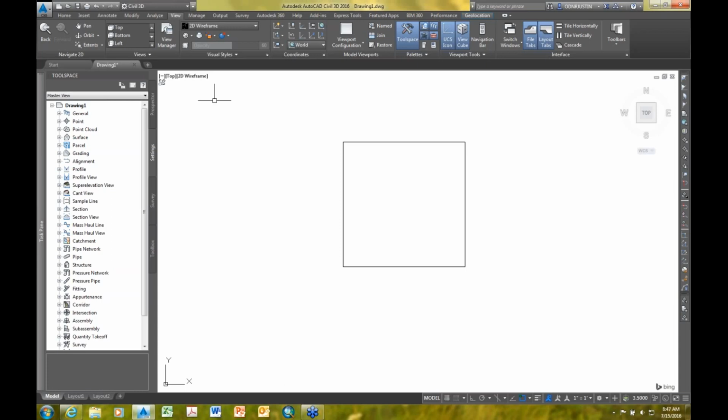Chances are you have somewhere a survey point or a line or a feature of some sort drawn miles away from the rest of your drawing, and your drawing is actually just little tiny dots showing up on your screen. So that's one thing you can clue in on if you're having issues: just zoom to extents. So here's my rectangle in model space, and it's 10 by 10.